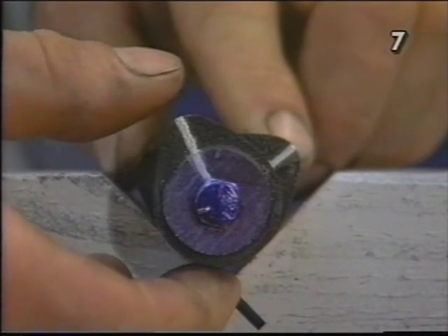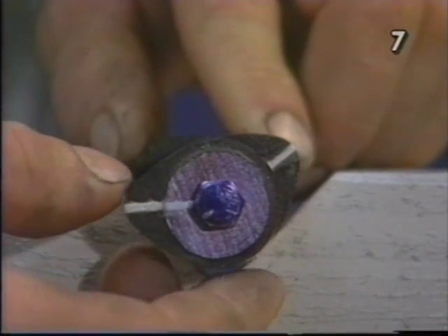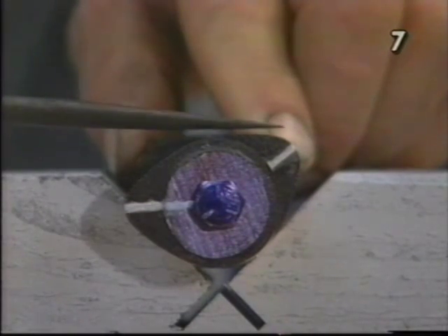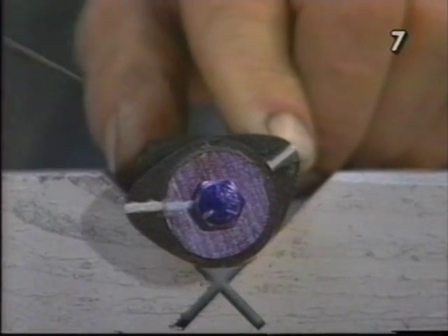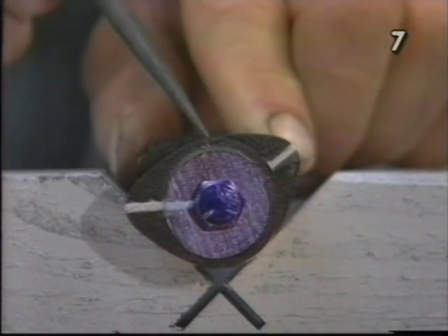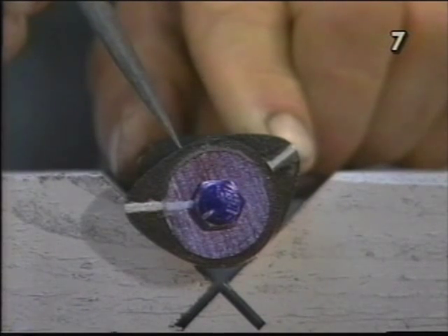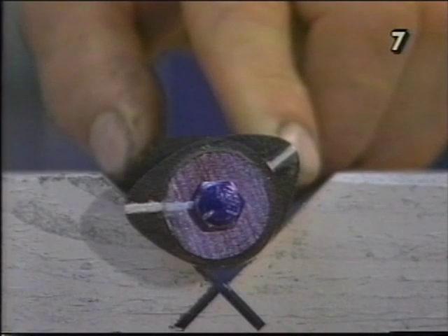If we were to increase the separation angle, and we're going to exaggerate it to make it clear, now we have a very large angle, a very large distance between the intake and exhaust center lines. At this time, it's very easy to see that the exhaust valve would already be closed just before the intake valve starts to open. This camshaft would have little to no overlap designed into it, which would designate it for very low RPM use.